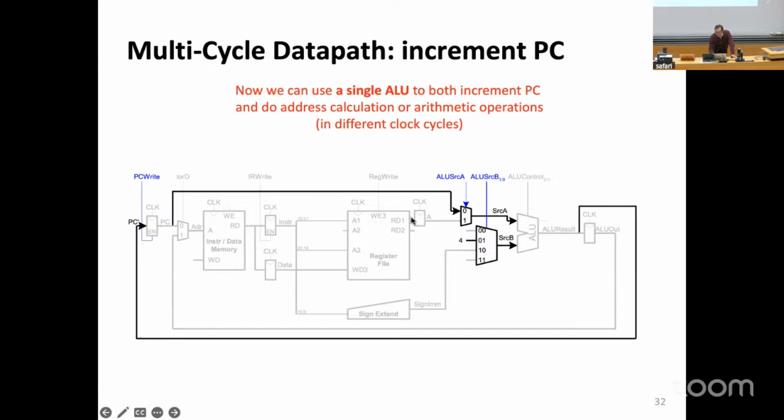Earlier, we input this register into the ALU. So you select between the program counter or the register. So there's an ALU source A multiplexer. There's also an ALU source B multiplexer that got expanded a little bit more than load needs over here, which is fine because it's going to be needed by other stuff. But basically, source B can come from this register, which we have not used yet.